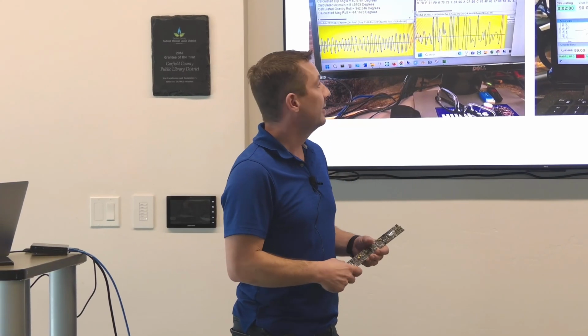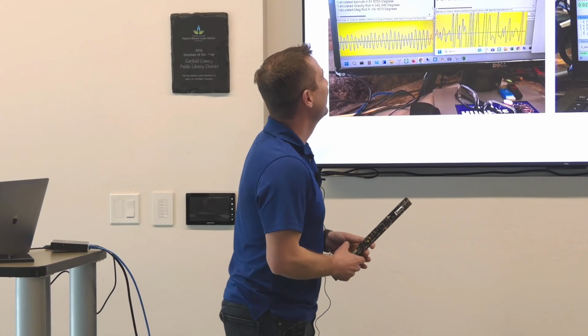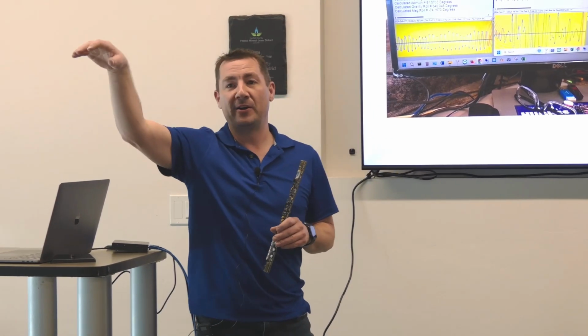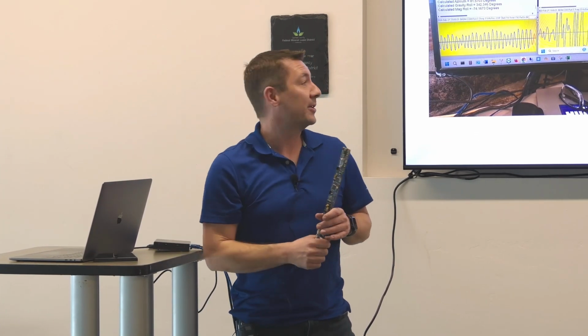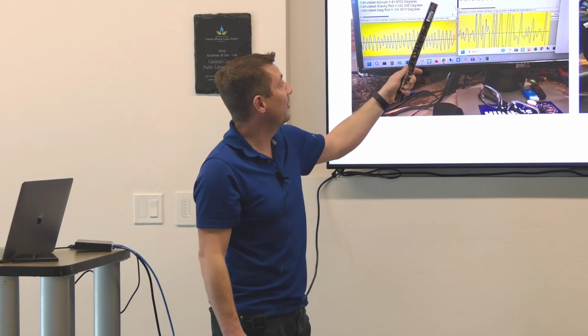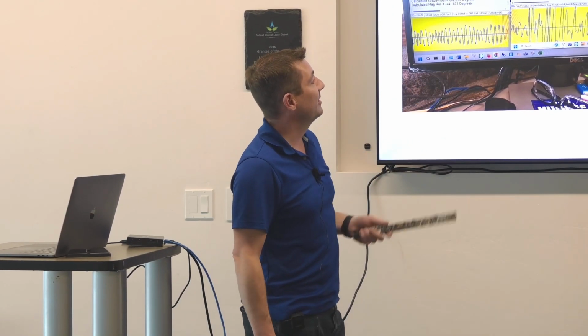And the yellow graph down the bottom there, that's your pulses? Yep, these are our pulses. This is what it should look like. This is what we don't want it to look like. In our specific company, we have a trailer that we can set on another well that's a mile away and transmit that data to the rig and decode it. What you're seeing here is the signal on the rig with all of the noise, which is not decoding. We're just getting overrun packets. Then we have what's on our remote trailer, being transmitted from a well that's previously drilled, and the signal looks great there.